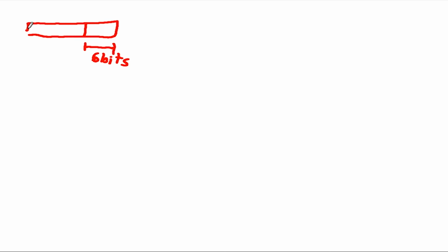It also had 64 cache sets, and therefore, in order to address 64 cache sets, we need another 6 bits, and therefore, we have set addressing which has another 6 bits. These two actually give the offset within a line, and these 6 bits provide the address for a particular set. So, later on, as we would see in the programs, we would require to know such information in order to build our cache based covert channel.